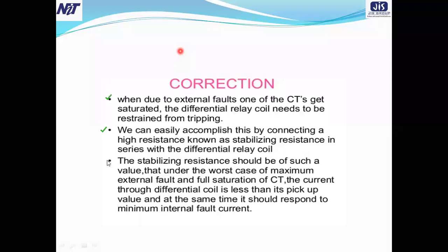The stabilizing resistance should be of such a value that under the worst case of maximum external fault and full saturation of CT, the current through the differential coil is less than its pickup value, and at the same time it should respond to minimum internal fault current. Okay, so in this way we can solve the problem of